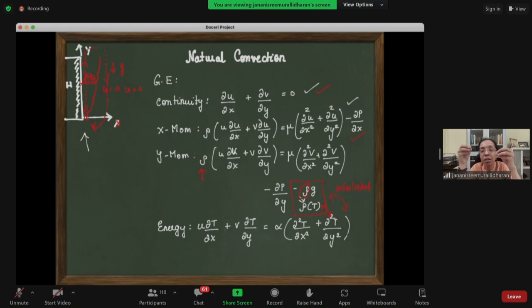The only real driver of the force, which is the source term, is driven by density difference. Within a small range, the flow is not going to be near Mach number, right? So I am just going to presume constant density for all other transport purposes, like advective and diffusive. But the flow driven by the source is the temperature difference, so only that term will be temperature dependent. Okay. So this is called the Boussinesq approximation, which is a very important approximation here.